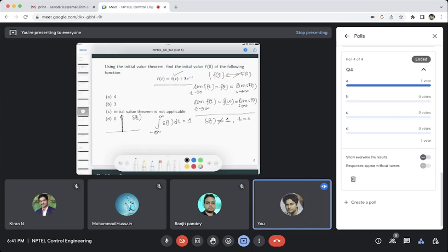So let's first analyze what this impulse function is. In the lecture video, if you have noticed, it is just an approximation of some signals. Let it be from minus a by 2 to a by 2, with height 1 by a. Then the area will be 1. If the width is a and the height is 1 by a, the area will be a times 1 by a, equal to 1, right?